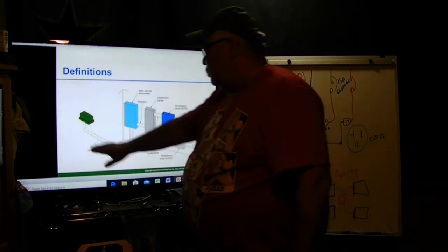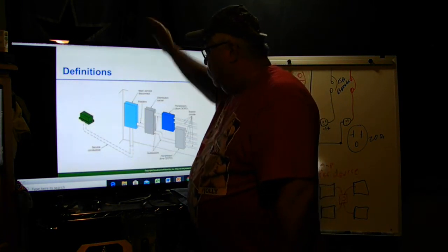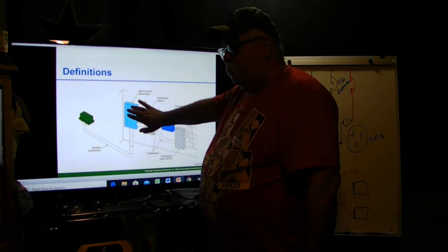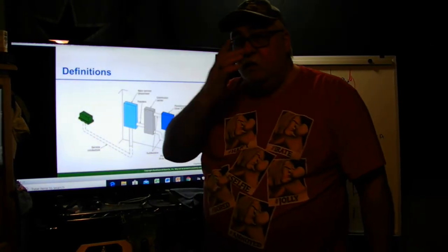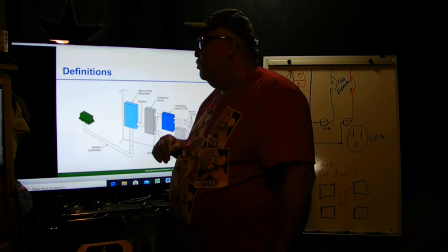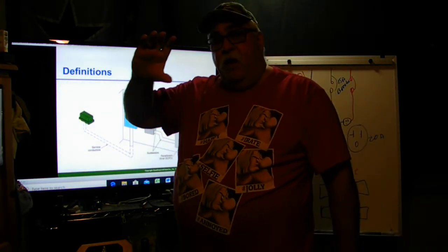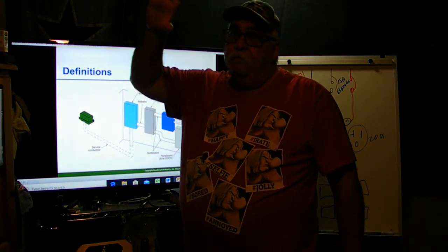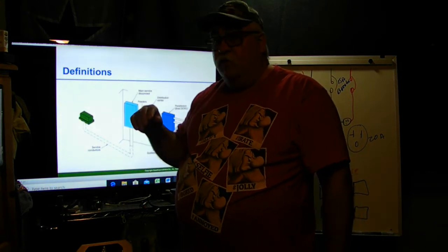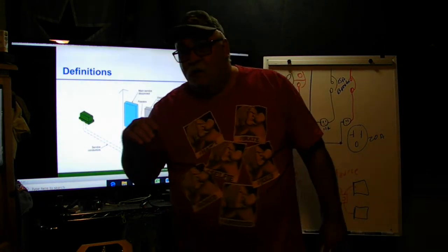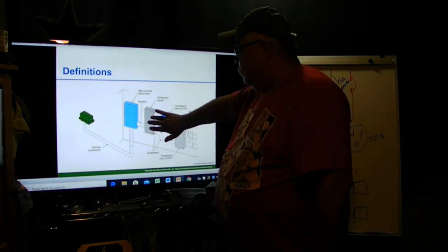So here is our service that's usually done by the utility, whether it's underground or overhead. This is where the meter and your main disconnect are. A lot of times this may be outside, more in commercial than in residential. It'll be outside where you have maybe a 400 amp, 600 amp fuse or breaker feeding, and then it goes to a distribution center.